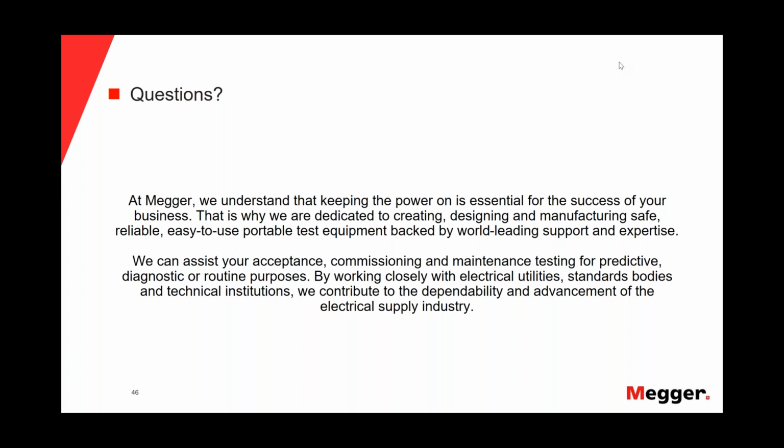I will not be concerned about water trees in the cable, because for water trees we need water inside of the cable and electrical stress. So I will not be concerned about the water trees, but maybe the jacket. For that reason, I will recommend to test the jacket, and maybe a commissioning test with the VLF, and maybe to see if there are some issues with the bend of the cable, maybe also the partial discharge test. Those are the three tests I will recommend.